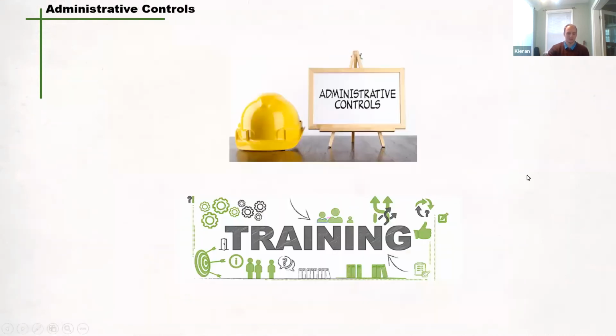So we'll move to the next thing. We just went over some engineering controls and ventilation. So we're going to look at administrative controls, as they're called. Administrative controls are as simple as a work practice control, so changing the way people work. So we could do a few things like a work schedule. If exposure to indoor pollutants can't be reduced otherwise, then we'll do it through scheduling. This way we can reduce the amount of time a worker is exposed to a pollutant.